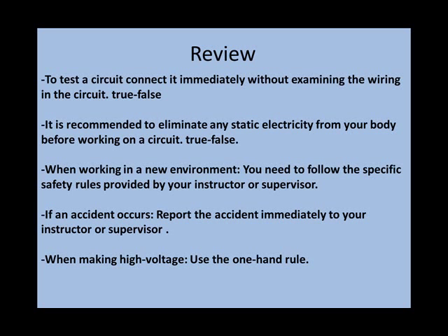If an accident occurs, report that accident immediately to the supervisor or instructor. Yes, you do need to provide that immediate information to the supervisor or instructor by reporting that accident, whether it's a personal accident, an equipment accident, or a piece of equipment or tool that is not functioning properly. You need to report that to the instructor. And when you have to make high voltage readings of current or voltage, you always need to use the one-hand rule, using one hand only, not both hands. That way you'll be safeguarded, and if something happens, an electrical hazard or electrical shock, you will likely be protected by not using both hands.